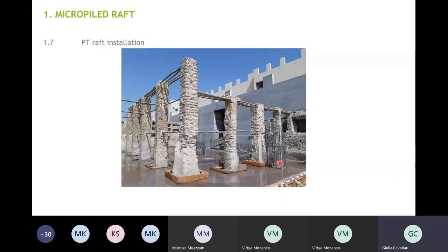And this is a picture showing after the casting of concrete. Special attention had to be paid to the curing of the concrete to prevent early cracking and to achieve a smooth surface and uniform pigmentation, because there were not going to be any finishes on top of the slab.